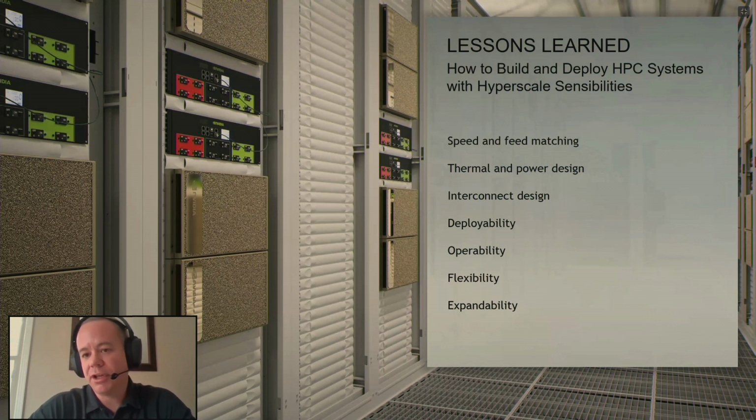Selene is our 4th generation design that we've deployed internally, and we have many customers that replicate and deploy our designs. Architecturally, we think about how to build out the data center and how to deploy these systems. There's a lot on speed and feed matching, right? How much CPU to GPU to NIC to storage. Thermal and power design: how do you fit into standard data centers without requiring custom-built racks? So nothing with ultra high density, allowing us to scale from 7 kilowatt racks all the way up to 50 and even higher kilowatt racks. And a lot on interconnect design, which I'll talk more about.